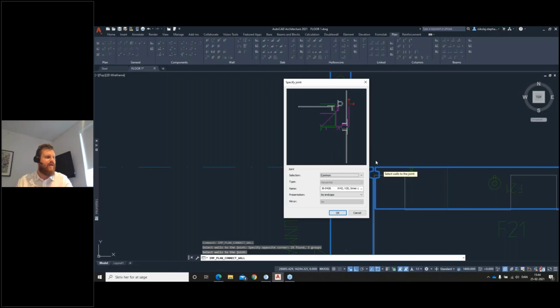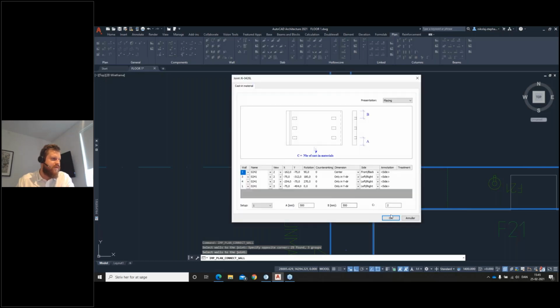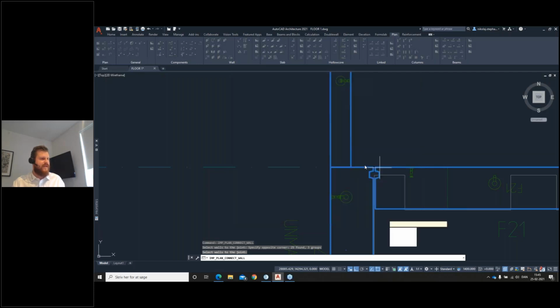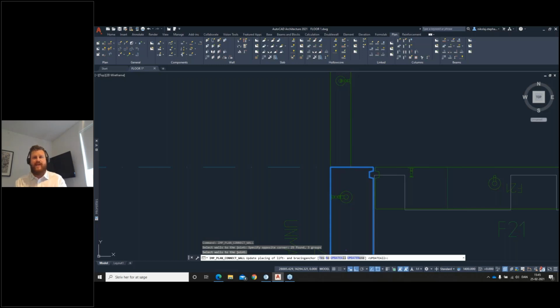So now when I do this instead, now it will show me you have these 2 types you can do. You can do a wire loop, you can do plate. And for you guys, of course, to use the software, you can do your own connections. I did the wire loop before. I want to do the wire loop again here. Some rules about how many we want. I can put a center distance in, which I did with the others, or I can just put a number in. In this case, I will select it's okay to put in these 2 here. When I click OK now again, it'll make the connection for me.